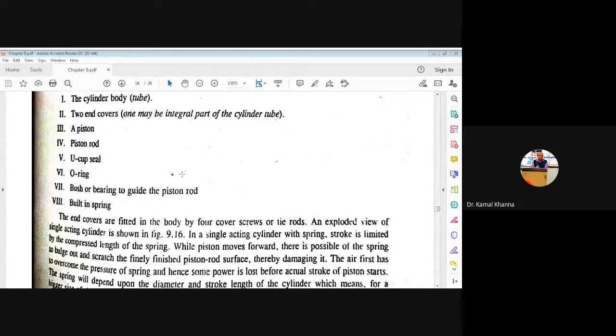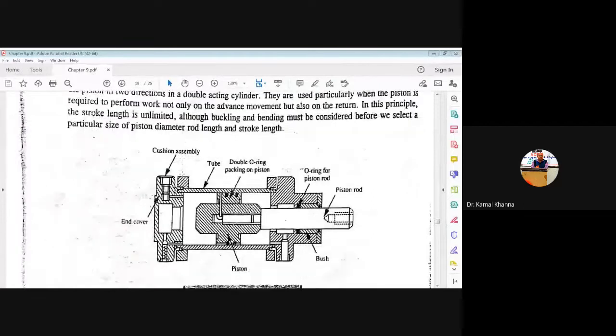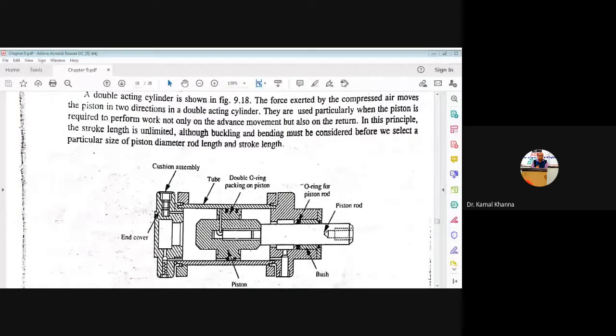So for the construction, this is the double acting cylinder. You can see the piston is assembled in the middle portion. We have a double type O-ring installed here. Why have we installed a double O-ring series here? Because the piston moves either way, to the left or to the right, as per the delivery stroke, and it provides a delivery stroke at both ends. Whereas in the single acting air cylinder, we get the delivery stroke on a single side only, once with the single motion of the piston.